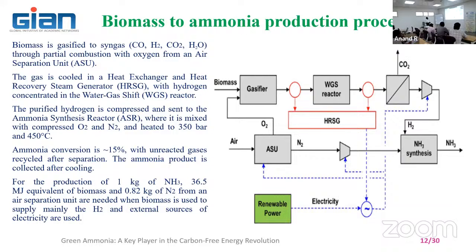Normally, this is a good system actually because if you supply air into the gasifier, the formation of oxides of nitrogen is also there. If you separate out the nitrogen and oxygen in the air handling system itself, and supply only oxygen, there is no possibility of oxides of nitrogen coming out from the gasifier.